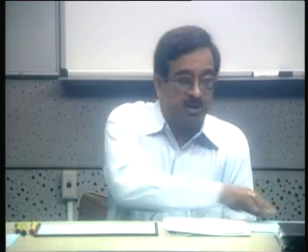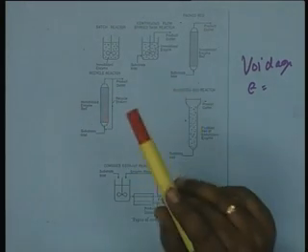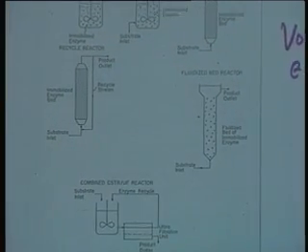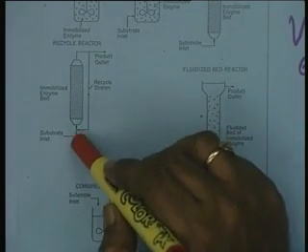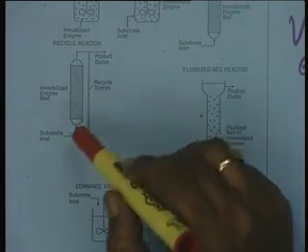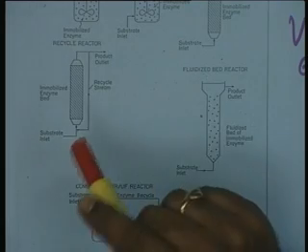Now, also an alternative situation in enzyme reactors is that sometimes we tend to develop reactor designs for various reasons, because of the requirements of the reaction. For example, in the case of a recycle reactor, as you notice here, although it is a packed bed reactor, just to increase the linear flow velocity to overcome the external film diffusion, we may like to have a recycle stream so that the linear flow velocity is increased, but ultimately it will end up in a non-ideality from the plug flow behavior.